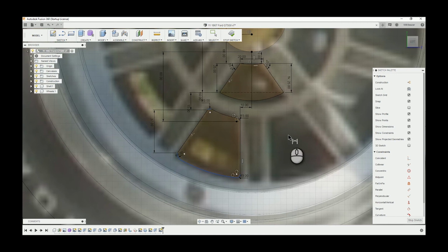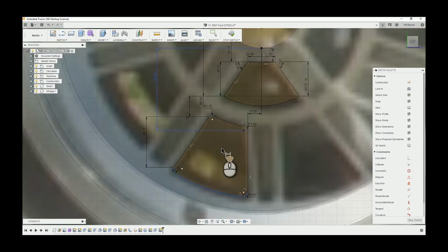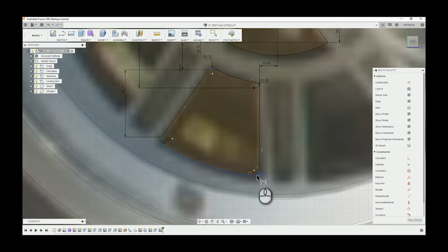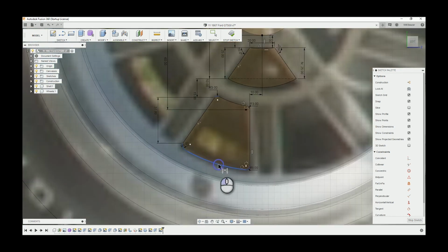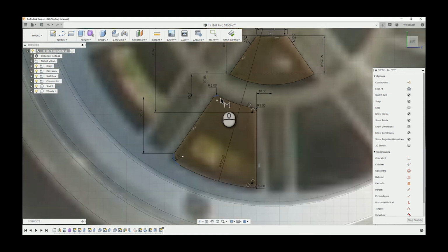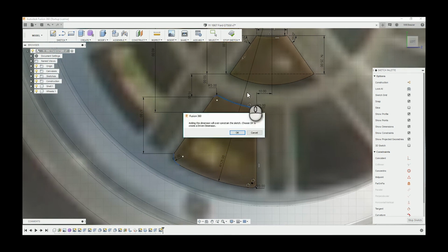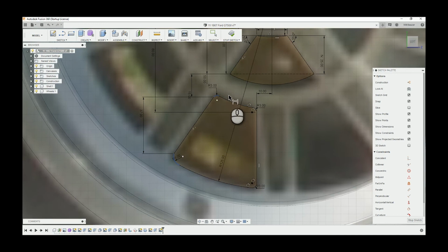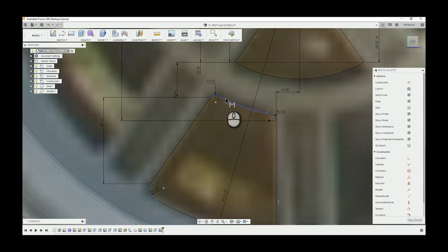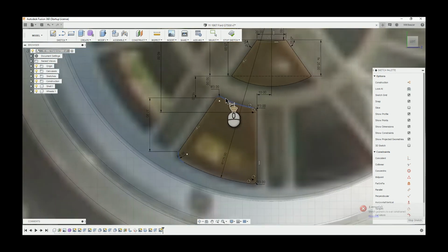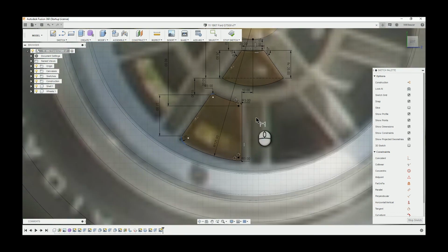One of the things I do in a sec is I just get a bit lazy, really. So once that line is constrained, what I should do is constrain them all. But because I'm trying to get through this project in a day, usually they're not going to move about on their own. So I trust that the sketch will stay in the same place. I just get a bit frustrated, so I just want to move on. So you'll notice I leave those two corners, those little blue sketch lines, unconstrained.